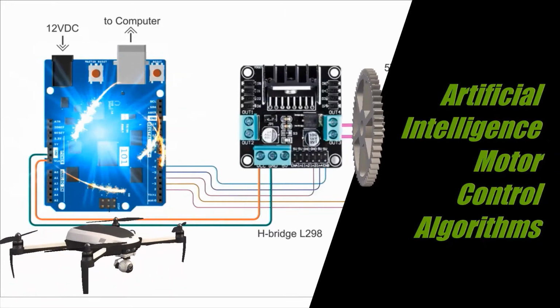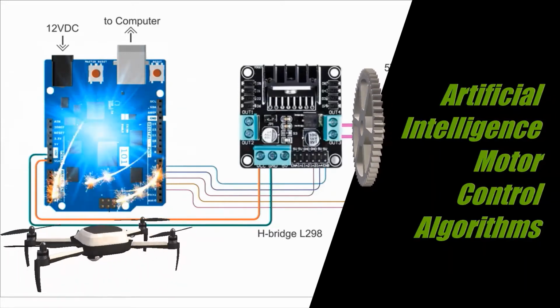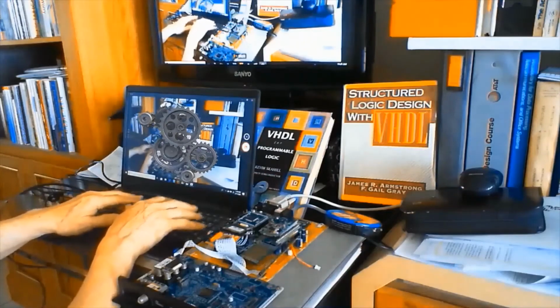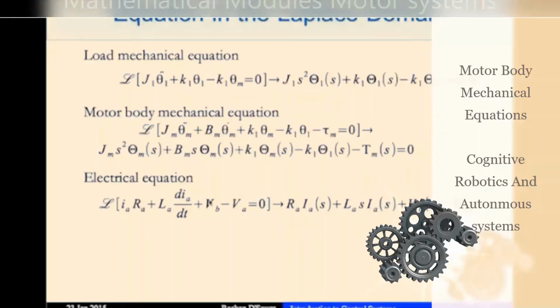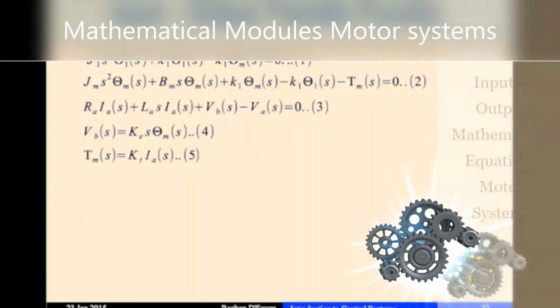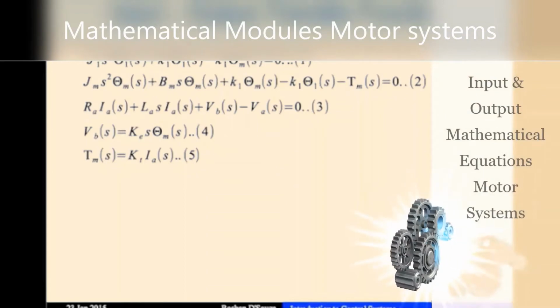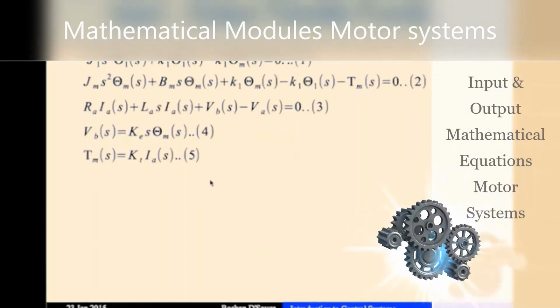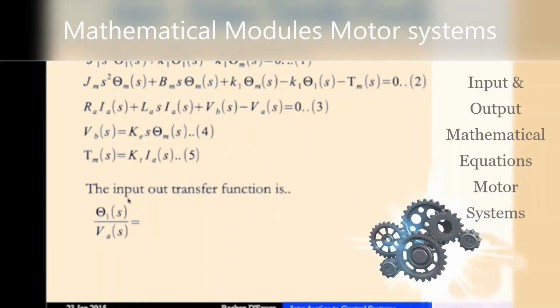That is, negative angles reverse the rotation. The output torque depends on both solenoid currents and the load angle, and the motor rotation causes a back electromotive force opposing the motion itself.